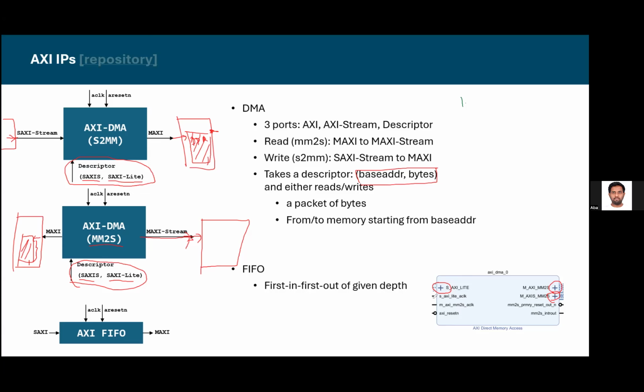And the most important limitation is that the Xilinx DMA is designed to be simply drag and drop: just connect these wires and get it working with the example, but not for actual performance or fine control, right? So what does it mean? It means that Xilinx DMA has this AXI Lite port, so you can write into these configuration registers and then it will start and do stuff. And writing into these configuration registers, this AXI Lite has a certain latency.